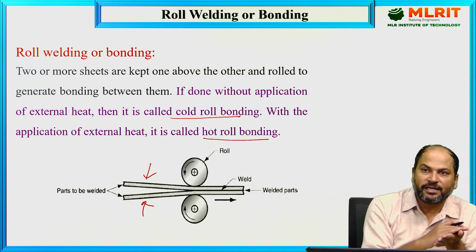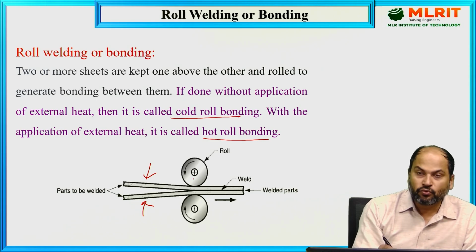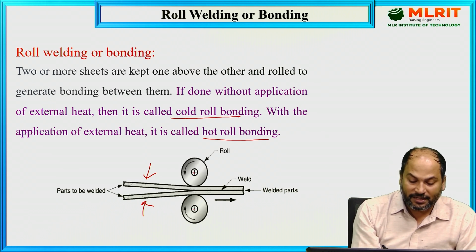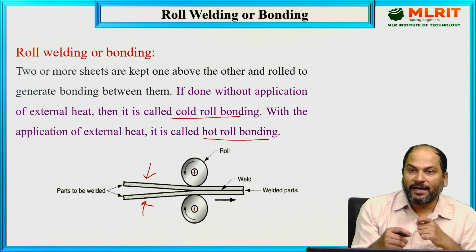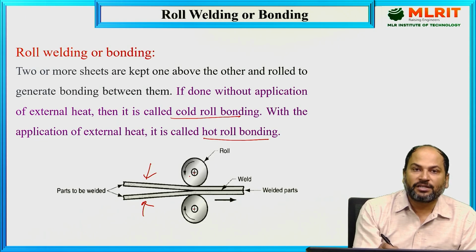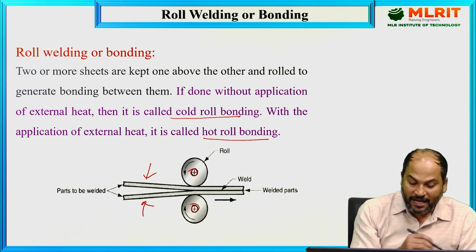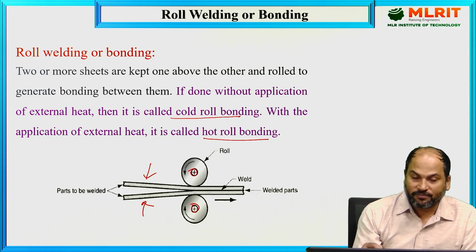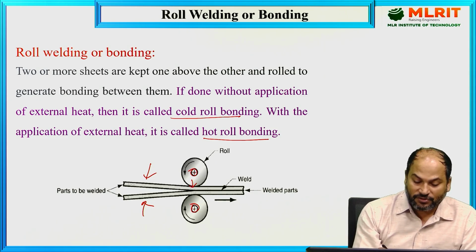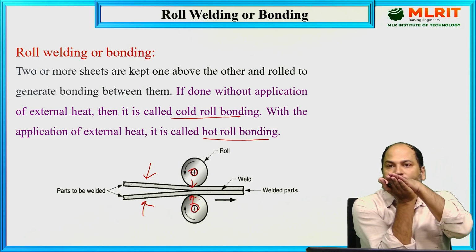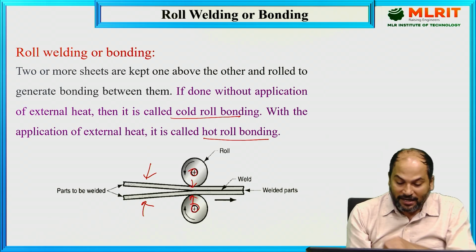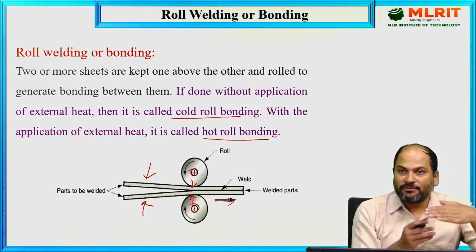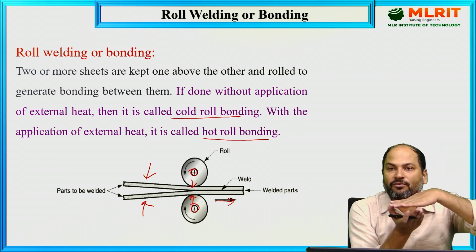And once it is completely removed, what we'll do is these two rollers will bring these two parts inside, and these two rollers are generally made of high carbon steels. They are capable of rotating on their axis. So this is the axis on which it is rotating, and this is the axis on which it is rotating, just like rolling. Once this workpiece comes inside, because of the compressive forces from both sides, these two parts will be welded together. You can see here it is moving just like a rolling sheet, and once it passes, pressure will be from both sides. It will be welded over there.